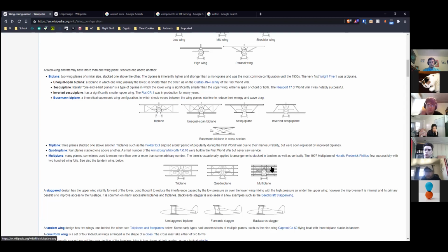So like this plane with, what is that, 6 wings or 7 wings or something. It doesn't have 7 times the lift as if you had just this plane with one of those wings, because there's a lot of air and stuff going on that will keep it from scaling infinitely like that. The other big challenge is that you don't want the wings to move in relation to each other, so that's why they all have these bracing wires. The reason this isn't very popular now is it ends up having a much bigger drag penalty than is worth it for the additional lift.